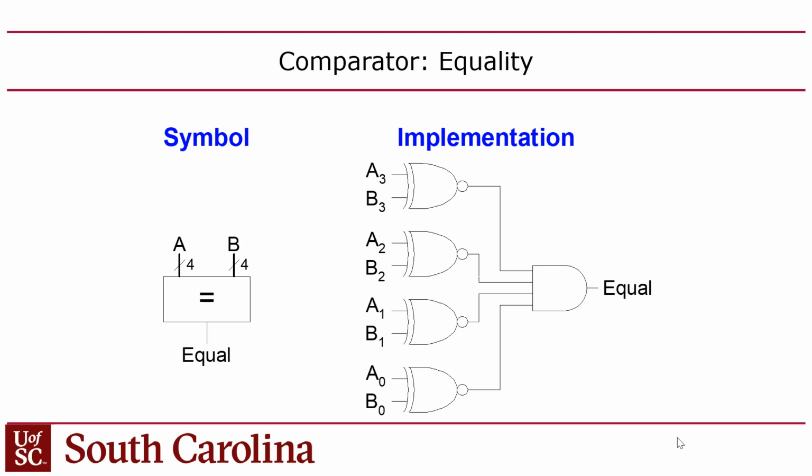Because in the subtraction method, if you have A minus B and they're 32-bit values, then you have to send all those 32 bits into a single OR gate, or a NOR gate, because you want to make sure they're all zeros, right? So I don't know if the way we do it in class is any better. Actually, it might be worse. This might be better than the one we've got in our ALU. I haven't done an in-depth analysis, but when I think about it, this might be a better way to do it.